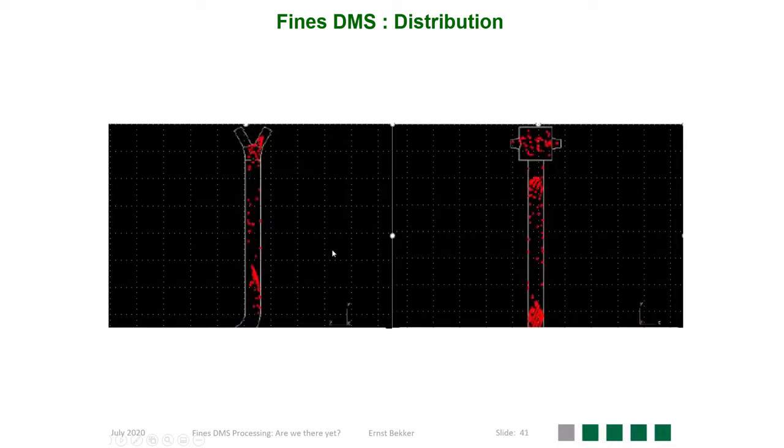In these pictures here, you can see the effect it has on the solids distribution. The Y distributor with the bend before it has progressively more solids on the one side, so more solids reporting to one outlet compared to the other. With the pulp distributor with a 90-degree outlet, there's proper mixing taking place and distribution is quite even. So having a pulp distributor with the correct feed pipe design is of utmost importance.